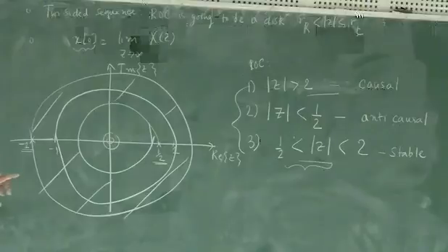So for that system, it's going to be stable. And so that's going to be a two-sided system, however, or a two-sided sequence, right? And so the moment I say it's two-sided, it cannot be causal because it has components of the signal that are non-zero for n less than 0, right? And so that is why for this set of poles and zeros that I have specified here, we cannot have a system or a sequence that is simultaneously stable and causal.